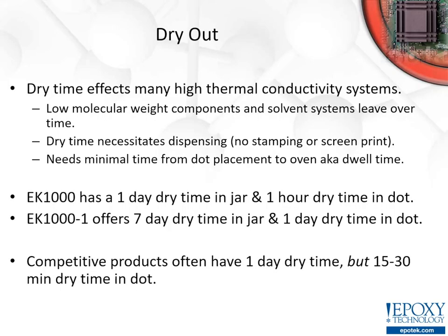Additionally, many of these high thermal conductivity materials use low molecular weight resins, diluents, or even solvents to achieve their high thermal conductivity. Dry out is absolutely a concern. And with some of the high thermal conductivity materials on the market, I've heard customers complain that they only have 15 minutes of processing time from the time the dot is placed to the time it has to be die attached and put into an oven.